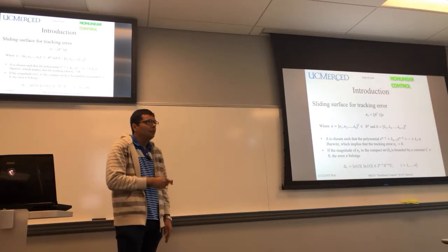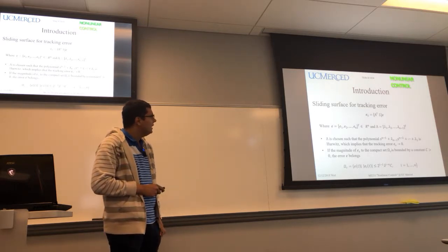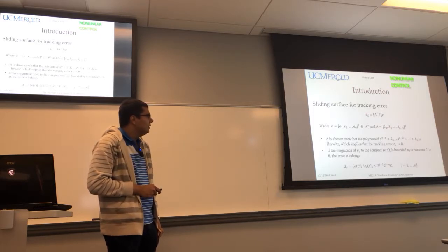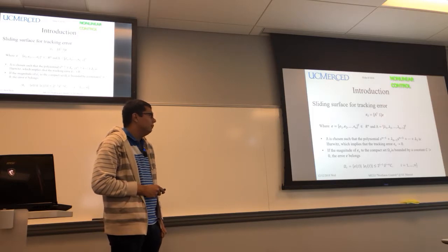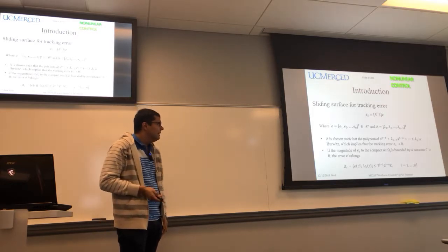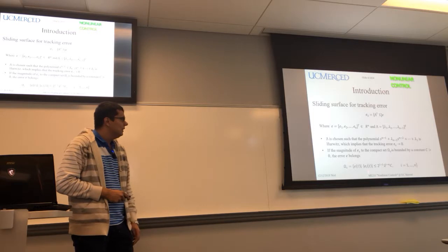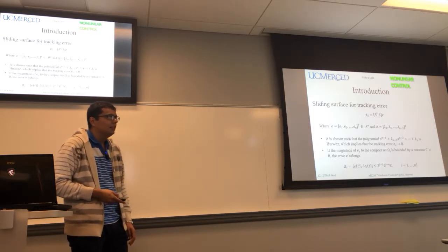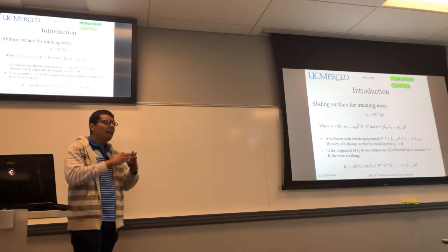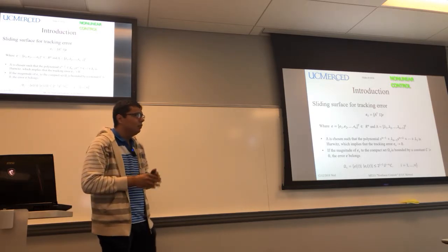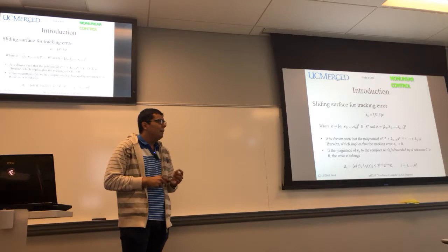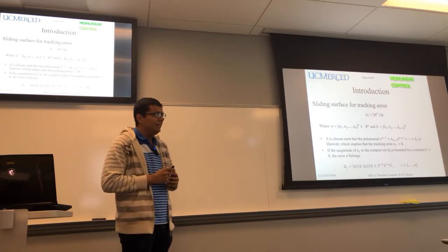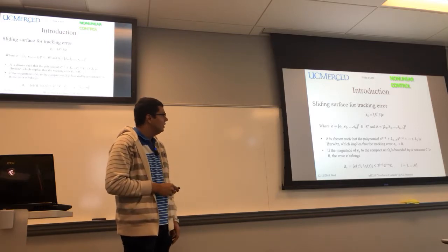Here you have different points that you need to reach. In this case, this sliding surface is based on this equation. This equation is basically a polynomial for the error. This polynomial is a Hurwitz polynomial, and it is convergent within the omega c subset. So we are limiting our control, in this case, to a specific part or a specific point of operation of our nonlinear system.